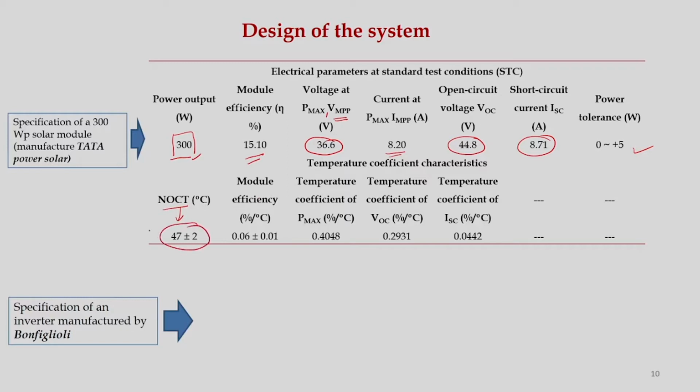This is also important, and these components are very important because the performance of PV modules deteriorates with respect to temperature and insolation. If temperature increases, performance decreases, and if solar radiation increases, performance increases, but if it increases further from the standard test condition, then temperature rise will be there, and that causes a lot of problems in the PV modules.